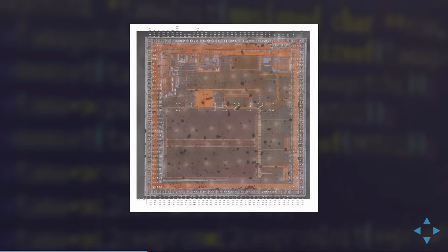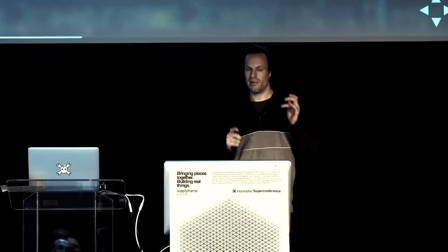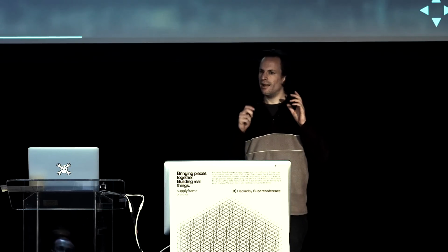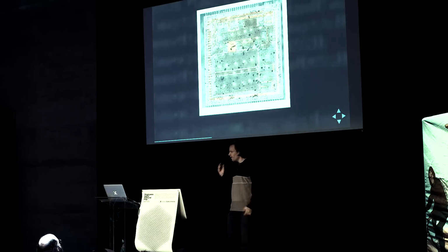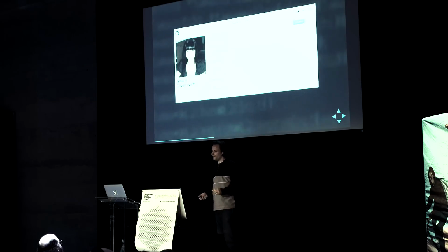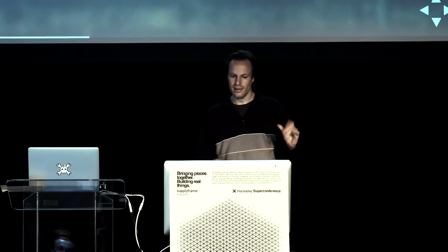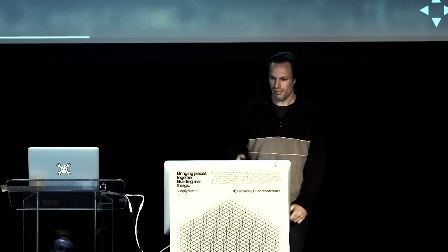She decapped the epoxy chip. She actually matched that to a commercial microcontroller. She got the data sheet. She figured out a way to inject her own code to run on that microcontroller and read out the internal ROM that way. And she disassembled that and used that to decipher all the secrets of the Tamagotchi. If you ever get a chance, look up one of her presentations. They are awesome, really. Luckily, she also is a believer in open source, and she has a GitHub account where you can find all the scripts and tools she used to get where she is. She also added dumps of the Tamagotchi ROMs and of the figurines you can put on top there. So that's really useful, especially when you don't have the hardware to do it yourself.